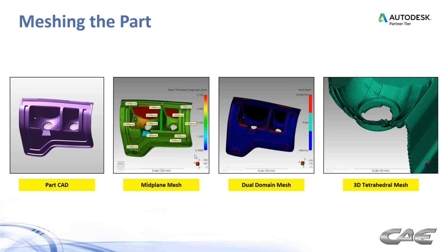So getting a better handle on complex filling patterns through complex geometry like that is one area where 3D tetrahedral meshes really shine. But there are some drawbacks too, on the warpage side and so forth, and it also costs you quite a bit of time on the solving side. So there are advantages and disadvantages to each one of these.